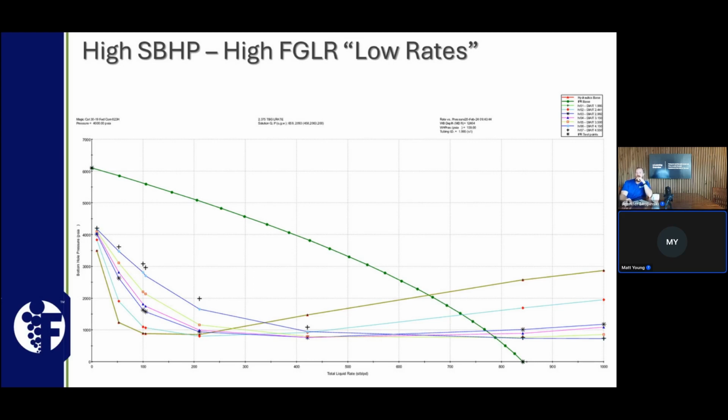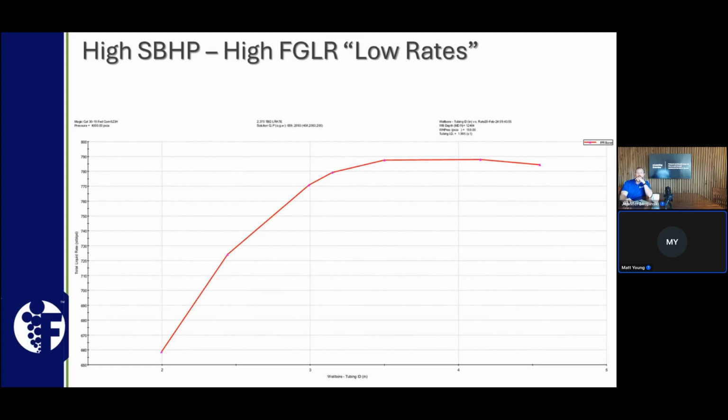And this one we find, if we look at our comparison of flow area versus liquid rate, we definitely see that we hit a cap when we get around our 2 7/8 or 2 3/8 inside 5.5" annular flow. In a case like this, any type of annular flow, if we had 7" casing, would not be ideal because we could actually hinder production just due to liquid holdup and liquid loading of the well.